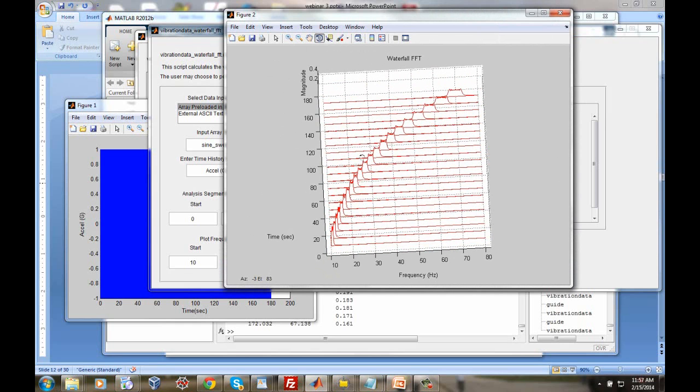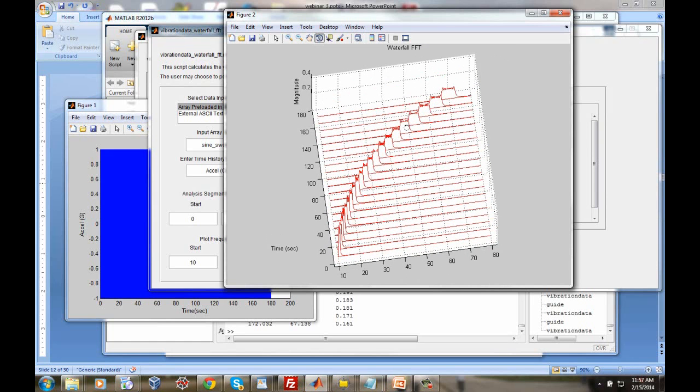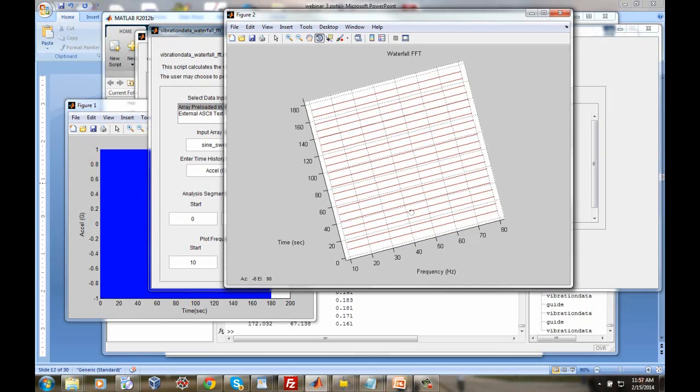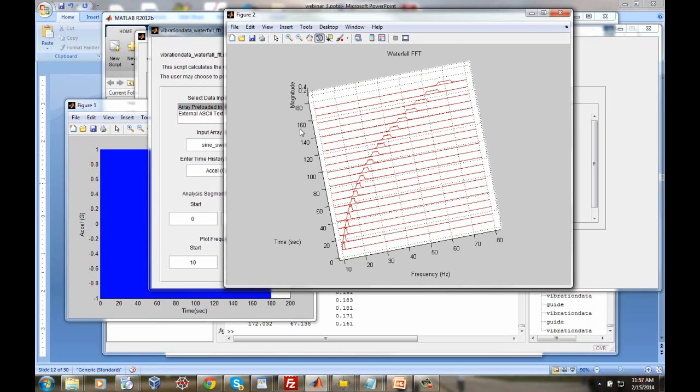But here you can see again, if we were to draw a smooth line through the center of the peaks here, through the center of each peak cluster, it would be a curved line. And again, that's due to the fact that we've got a logarithmic sweep rate. So we've got magnitude along this axis here. We've got time in seconds and frequency in hertz.